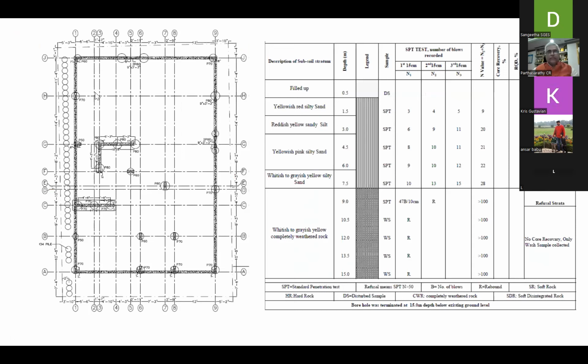Another project recently was a residential building, about a 5-6 floor building. There are a lot of monopiles being installed around, and a series of touch piles to retain the basement excavations, which ultimately collapsed during excavation due to rain, and these piles were all cast as single-pile monopiles. Some of the piles were tested, integrity was fine in some of the piles, and one of the piles, maybe this or this, was tested for a high strain dynamic test. Let me show the results in a bit.